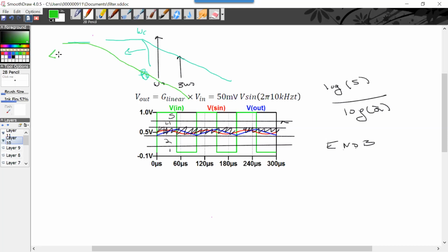However, this is your usable bandwidth. If I keep moving this closer and closer to 0, the more it will behave just like a DC power supply. If I wanted to listen to music digitally, I have to be able to play 44 kilohertz. So that's what my filter would look like, and then my harmonics would have to be out there. So one thing is we need to reduce that ripple.